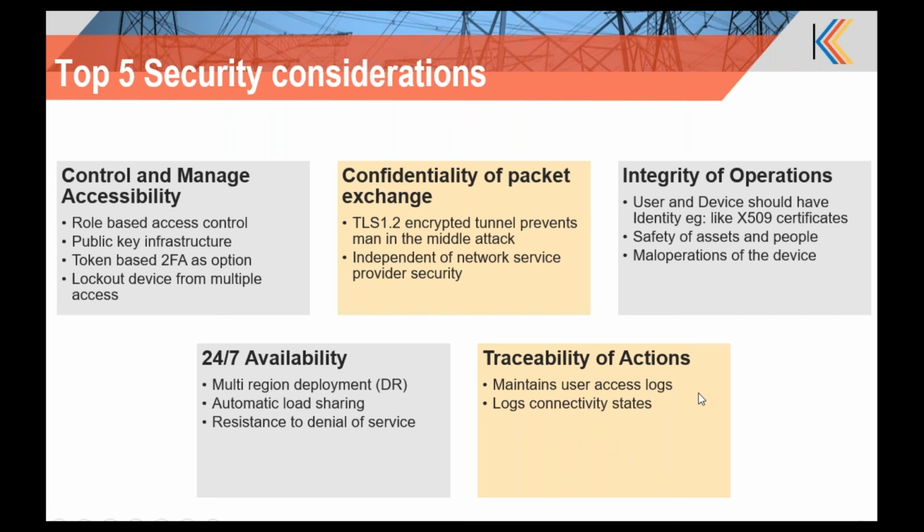And the traceability of operations or actions invoked by the user. For example, if a user is going to set particular settings in the inverters, all the operations which he does on these devices should be logged and should be available for future audit trail purposes, mainly for tracking and having ownership for each and every action taken by each individual user. And these logs should be available on standard repositories like, for example, a syslog server or a third-party syslog service.